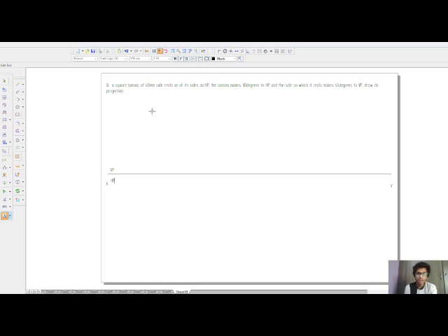Now, first we should determine whether the surface inclination is with HP or with VP. If the surface is inclined to HP, then the true surface lamina will be below the XY line, that is on HP. If the surface is inclined to VP, then the true surface lamina will be above the XY line, on VP. Here, the surface is inclined to HP, so the true surface lamina will be below the XY line.